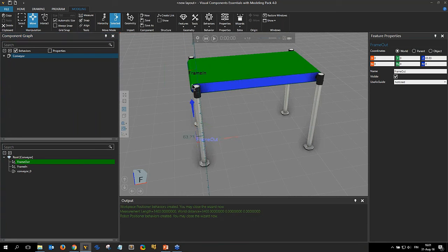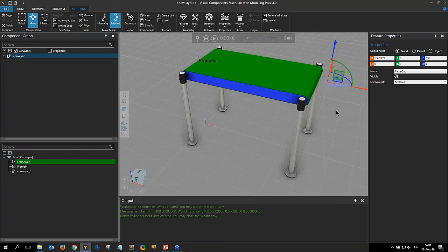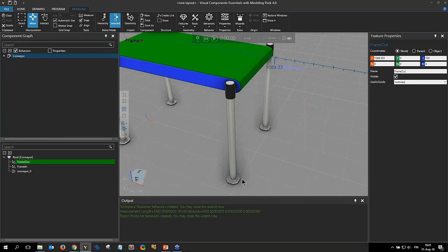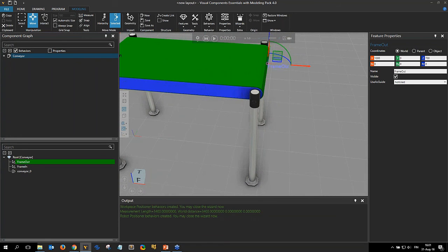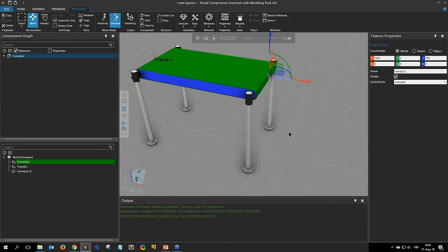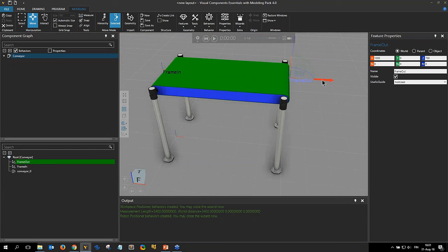and the frame out would be level with that, but maybe project it with control there. So I drag this arrow, hold down control, and snap it with that, and it projects that axis with that. Very good. If I want some gap between the conveyors when I connect them, I could make this overshoot, for example, 20 millimeters. Then there would be 20 millimeter gap. So I put, for example, 5 millimeter gap there like that.